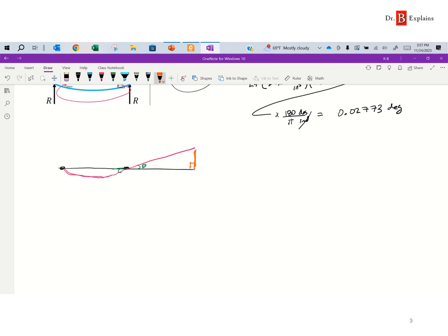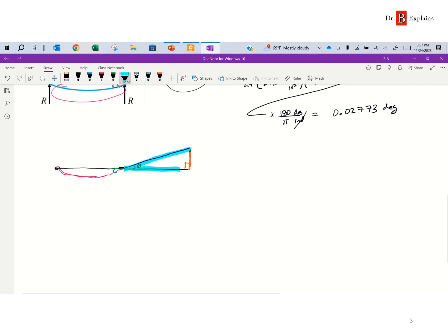And what we want to find out is what is this deflection here, right? Again, I have a right triangle, and what I know is I know an angle. And I also know, for example, this dimension. This dimension was 72 inches, right? And so I can use that to figure out this opposite side. So if I write tangent of theta is equal to the opposite divided by the adjacent, the adjacent being this quantity over here, which is 72.